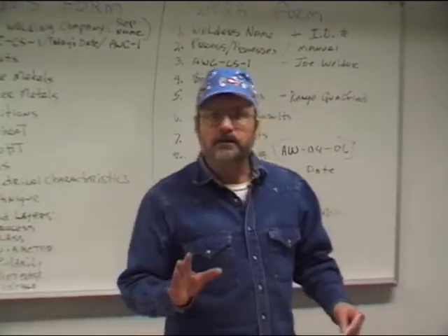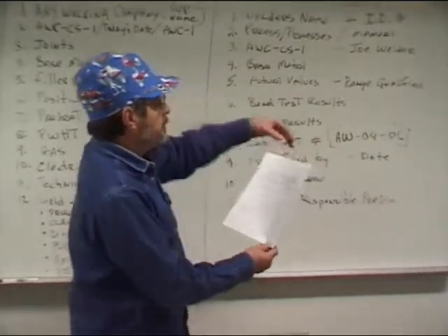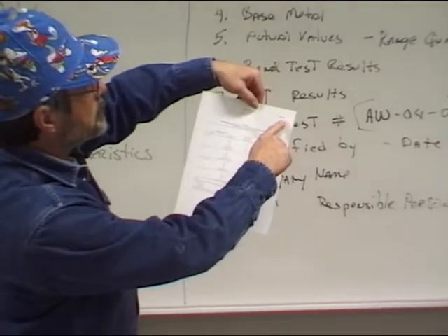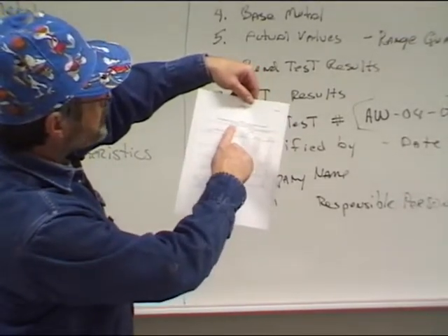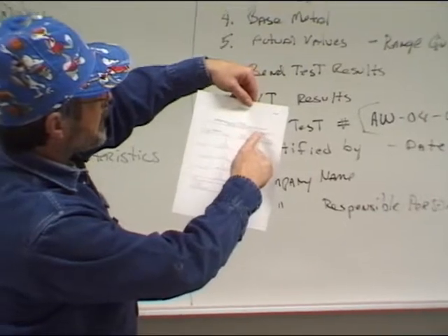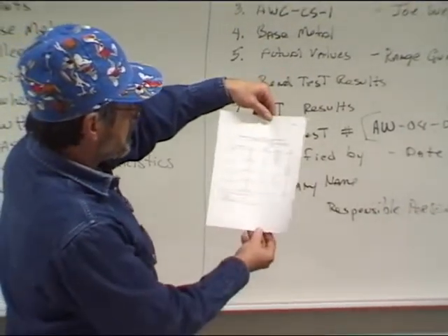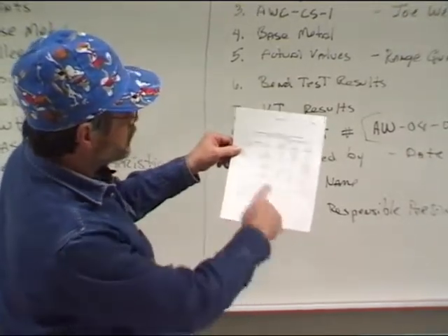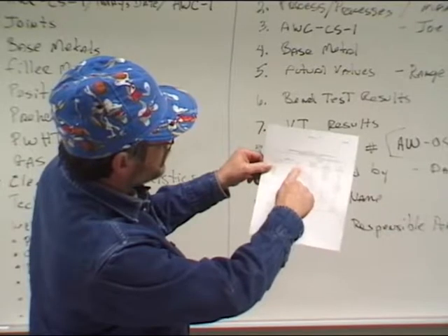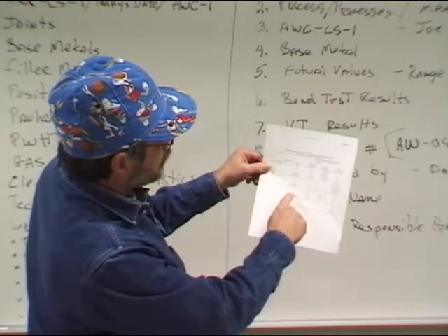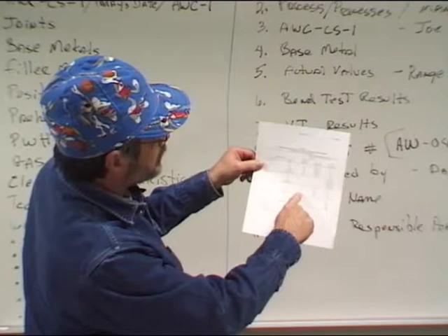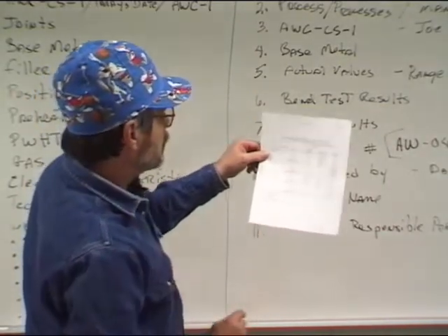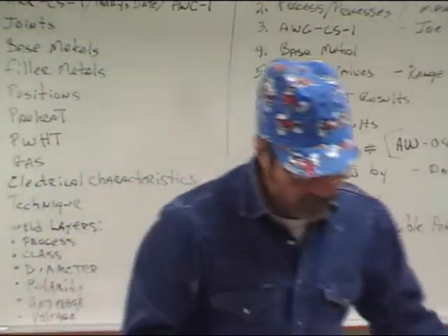Let me go over a couple of other documents that were in your student packet. Here we have welding data. It says QW-461.9, performance qualification, position and diameter limitations. Under our example, we were doing pipe groove welding, and we did it in the 6G position. So you'll come down here where it says position, come down, it says 6G, and you come across here, and that qualifies a person to weld in all positions. You just go right on across there and you see it's all, and all. So I put that in there for your personal use.